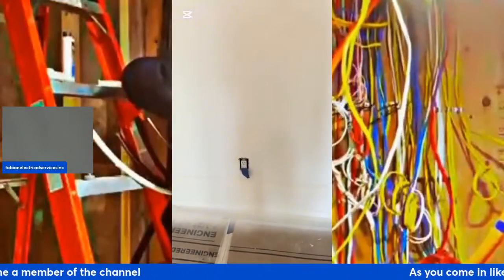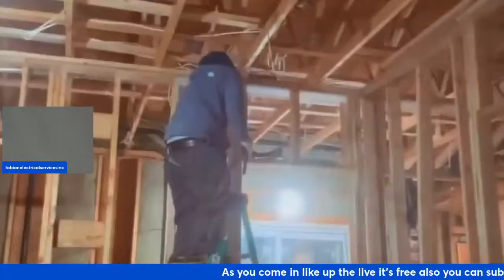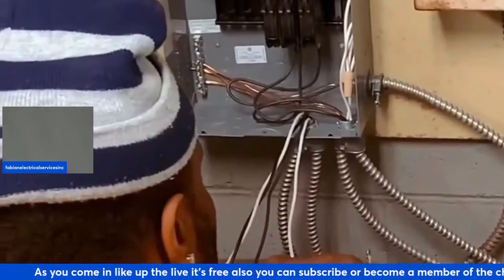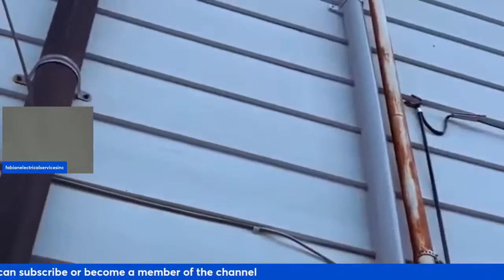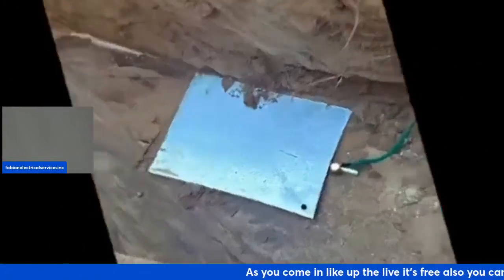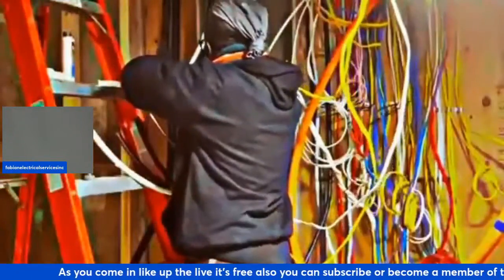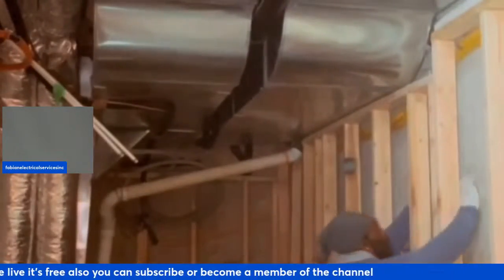You normally will run the BX to the first location, which would be the receptacle itself, and because the receptacle is in an area where it's not really considered a kitchen counter or any other receptacle that you're installing in the home that's a 20 amp, it does call for an arc fault. There's something called a dead front.